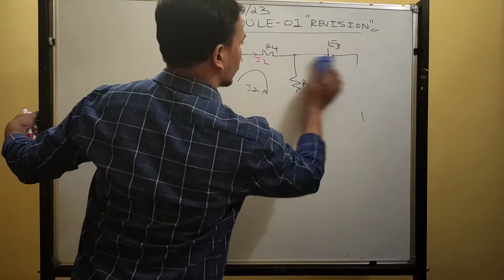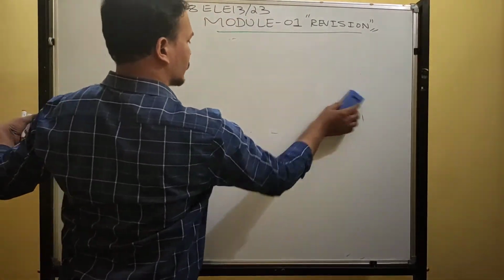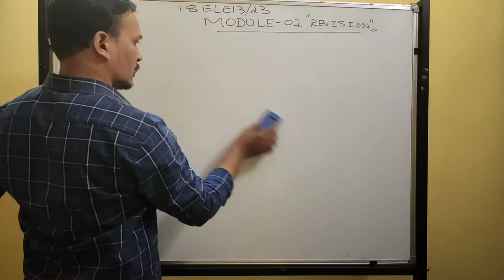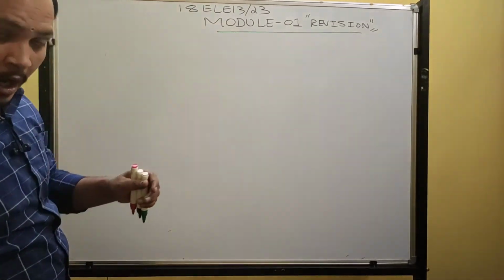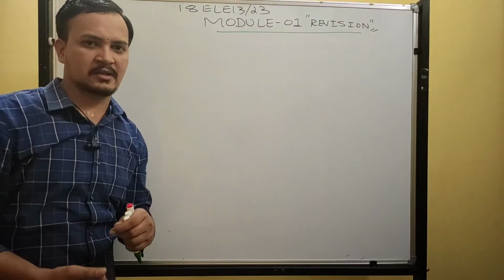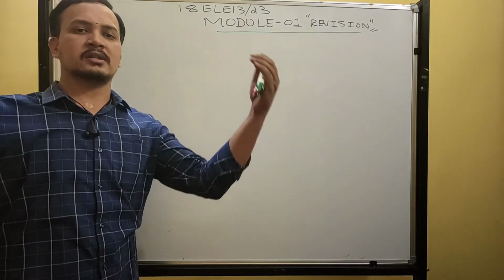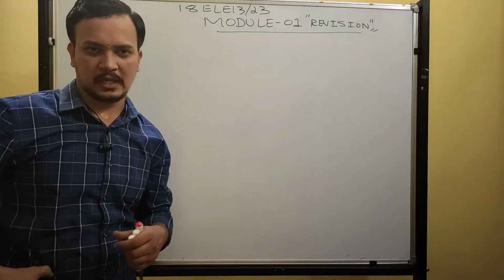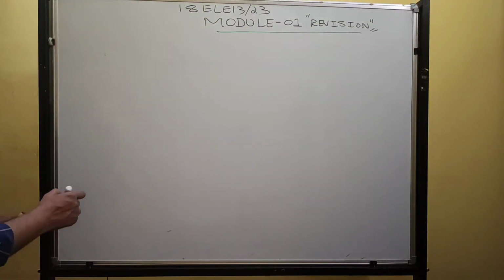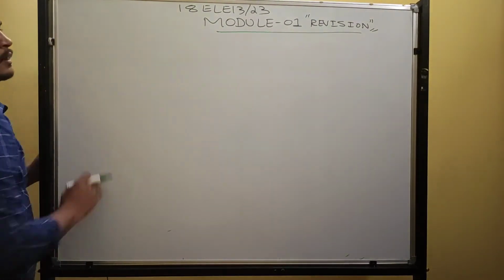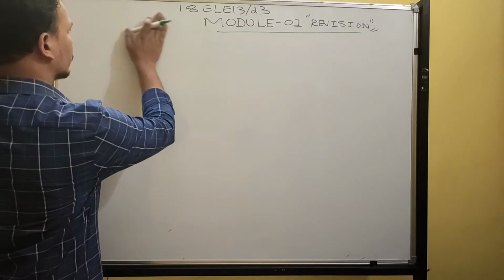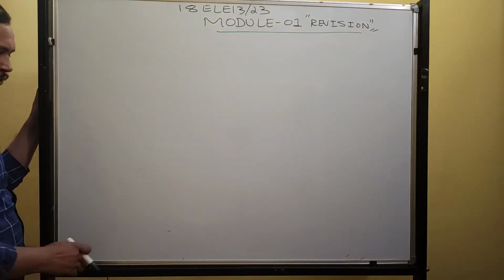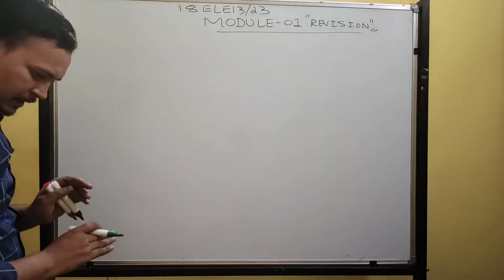So next, if any resistor is placed between 2 loops and the currents are facing opposite to each other, write subtraction. If the currents are coming in the same direction for that middle resistor, then you take a positive sign. So refer to the concept in the regular videos, that is class number 8 or 7. You can go through that. So this completes DC circuits.